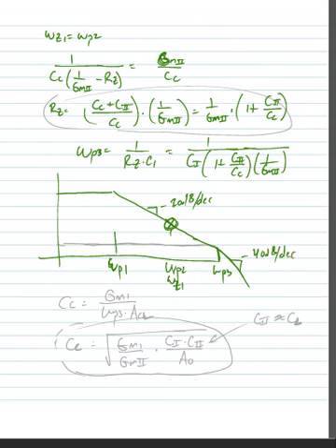And we know that if we want a 45-degree phase margin, we try and make our closed loop response intersect our open loop response at whatever the second pole frequency was, even if the second pole frequency is an effective pole frequency. And so our compensation capacitor, CC, is equal to big GM1 divided by omega p3 times whatever our desired closed loop response is.